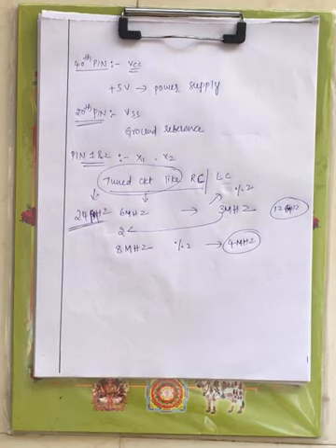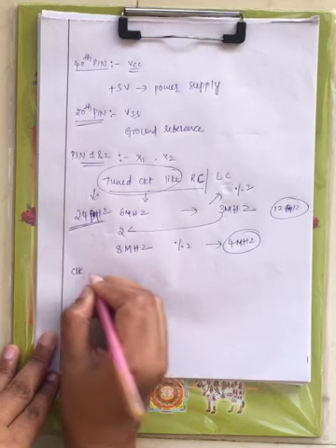The user has to have an idea about this oscillator frequency and the internal clock generation frequency. Remember, we are providing the oscillator or the tuned circuit like RC or LC at pin number 1 and 2. The oscillator will generate some frequency, and that divided by 2 is the operating frequency of the processor. We provide the oscillator at pin number 1 and 2 in order to give the operating frequency to the processor.